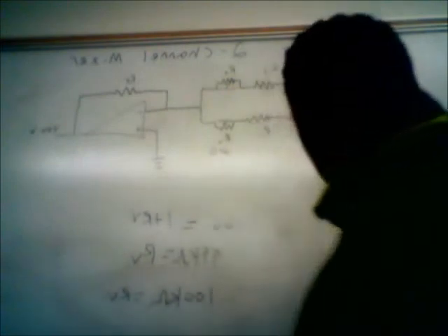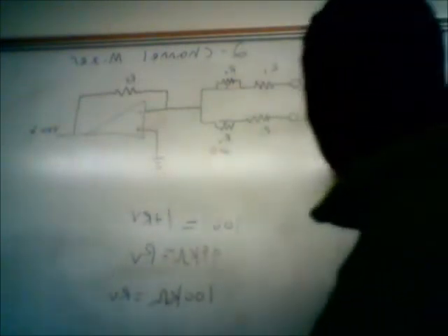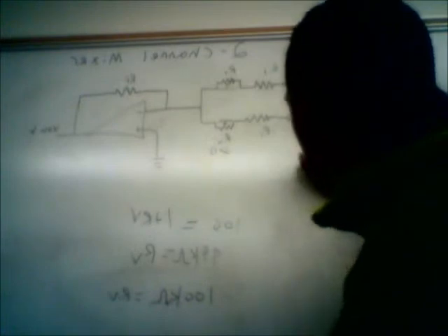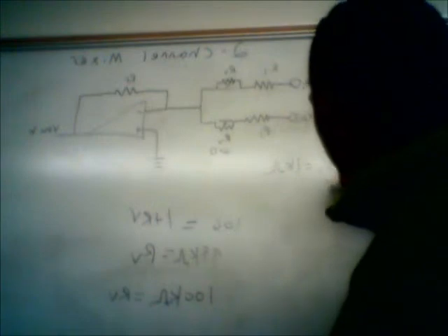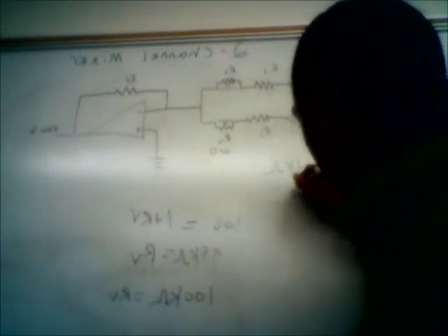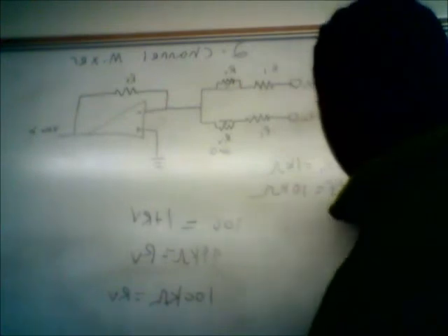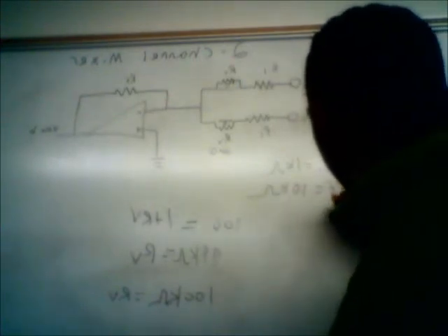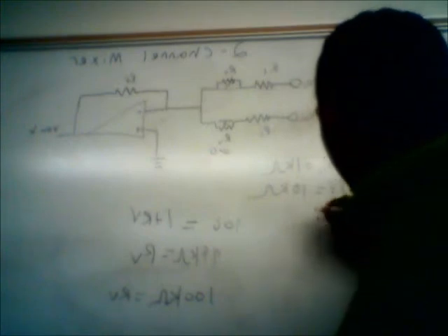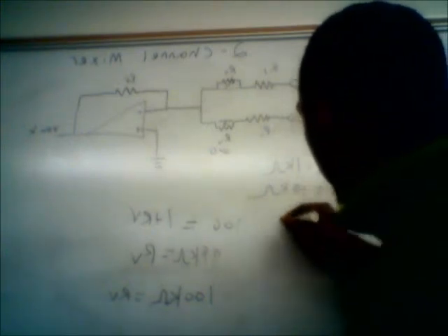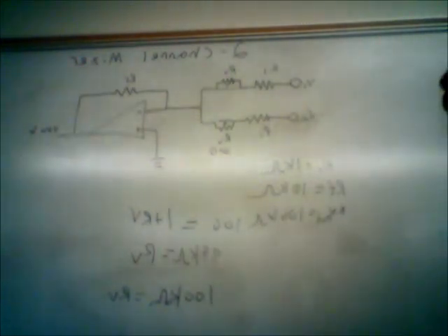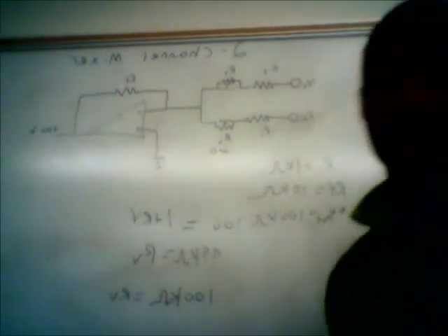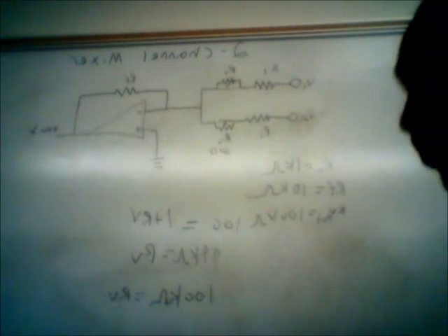So you have, see if you still see me here. Yeah. R1 equals 1 kilo ohm. RF equals 10 kilo ohms, and then RV is a pot equals 100 kilo ohms. Remember, this is a potentiometer. It's only going to be 100 when it's turned all the way to one side, and it'll go to 0 essentially, or usually like 0.6 ohms when it's turned all the way down.